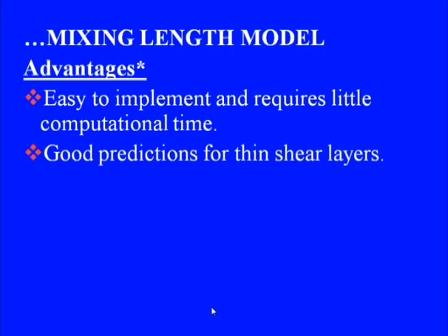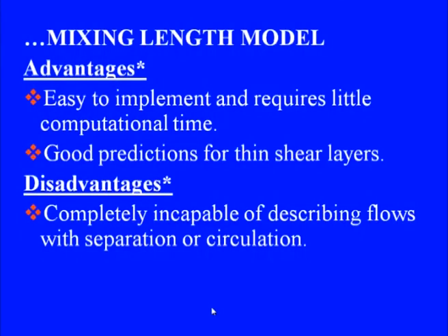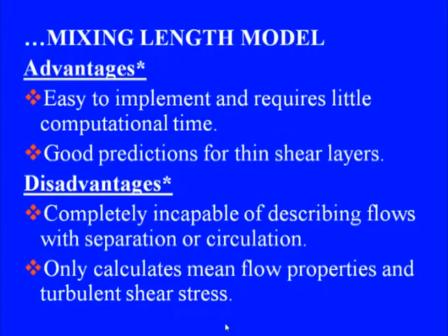It's very easy to implement and requires very little computational time in addition to solving our velocity components, and it gives pretty good prediction for thin shear layers. A disadvantage is it is completely incapable of describing flows with separation or circulation, and it calculates only mean flow properties and turbulence shear stresses. So this mixing length model is used only for the simulation of thin shear layers.